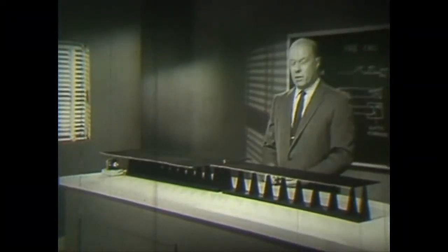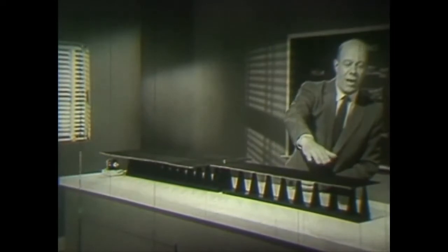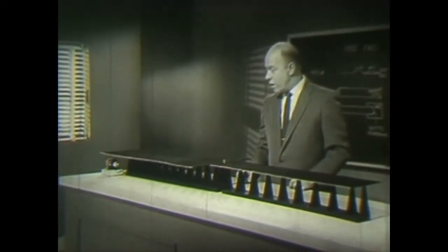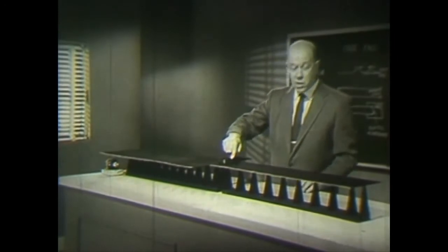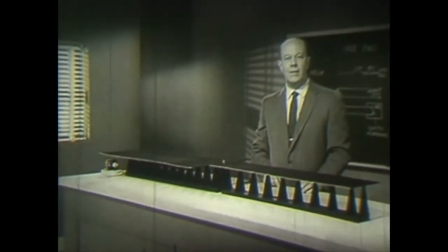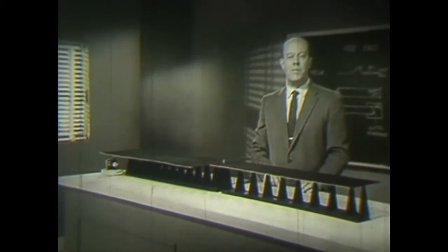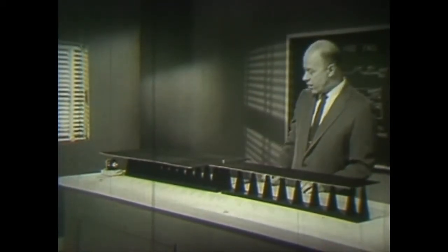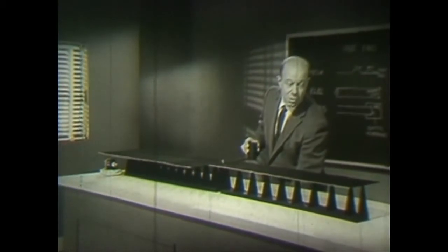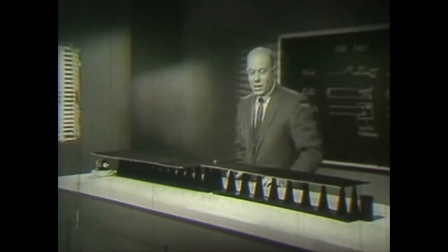At this point, where the two central wires are clamped together with this little clamp, there is an abrupt discontinuity in the impedance of the transmission path. A wave traveling slow along this medium will suddenly speed up when it crosses over into this one. This behavior is similar to what happens to a beam of light when it emerges from glass into air. Now, before I show you what I want to show you, let me clip this dash pot down here in a matching position to prevent the unwanted reflections from this end. It's this point here that we're really interested in.